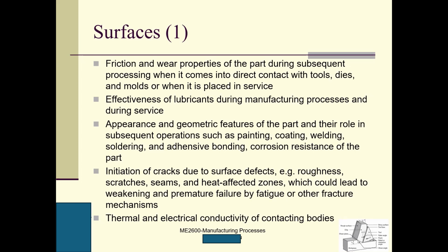So we might have the coolant, right? Have you guys ever operated some machines? Did you operate a dry machine, or do you use some coolants or other lubrications? Dry machine, right? I assume, because I cannot see the cooling system. The cooling is especially important when you machine very hard materials, titanium, nickel alloys, because when you machine this kind of material, a lot of heat will be generated.